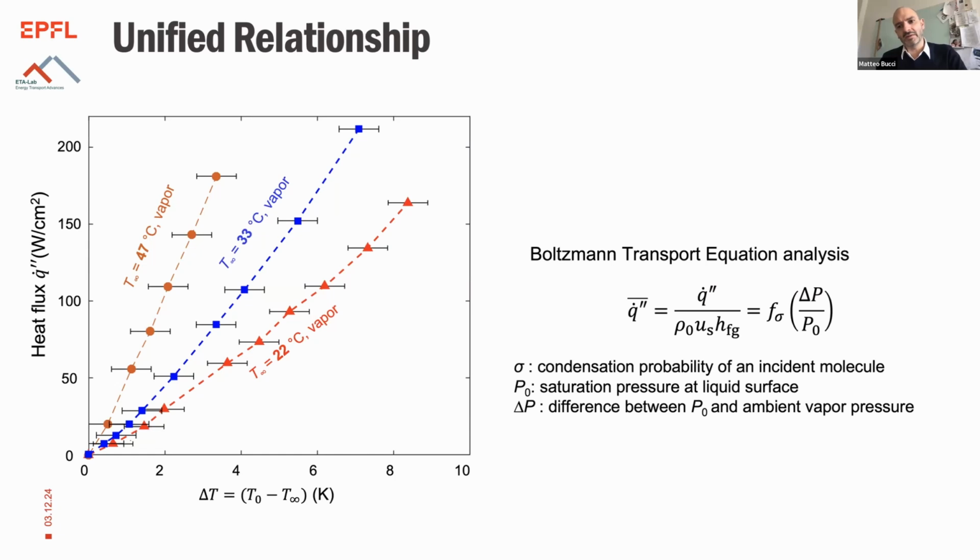I wonder whether this can be simply explained by considering the effect of vapor pressure on the curvature of the liquid vapor interface at the orifice. Because you have an equilibrium interface, and essentially the angle formed by the liquid phase with the solid will be determined by the vapor pressure here.